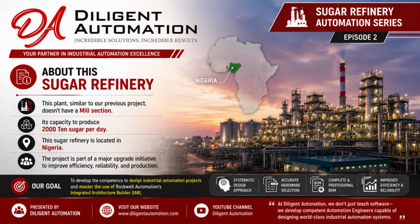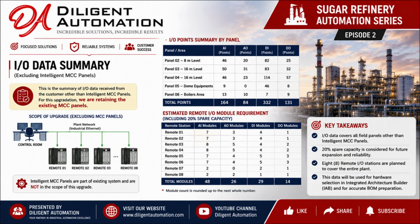Before we start selecting hardware in IAB, let us briefly understand the application. This is a large sugar refinery automation system with approximately 2,500 field I/O points. The equipment is distributed across different areas of the refinery, including the 8-meter level, 16-meter level, dome area, and boiler area. We also have multiple intelligent IMCC panels containing a large number of motor starters, soft starters, and variable frequency drives. So this is not simply a PLC with a few local I/O modules.